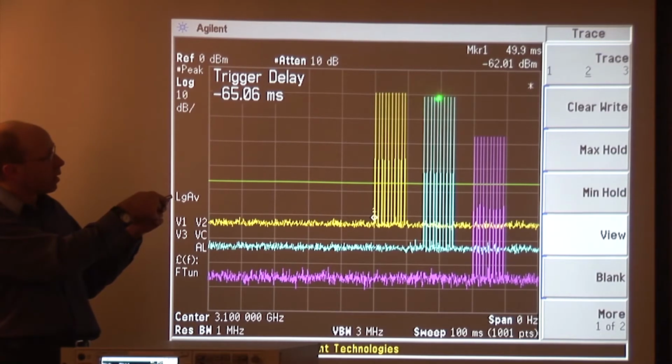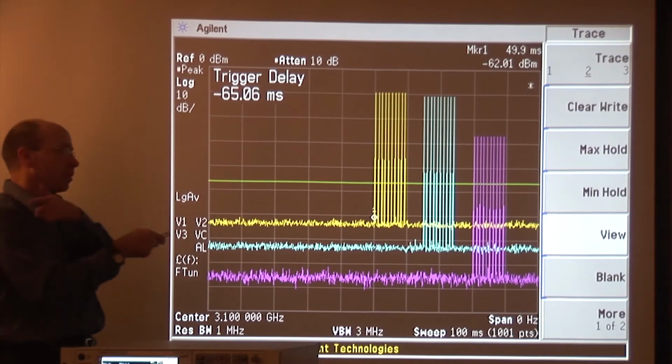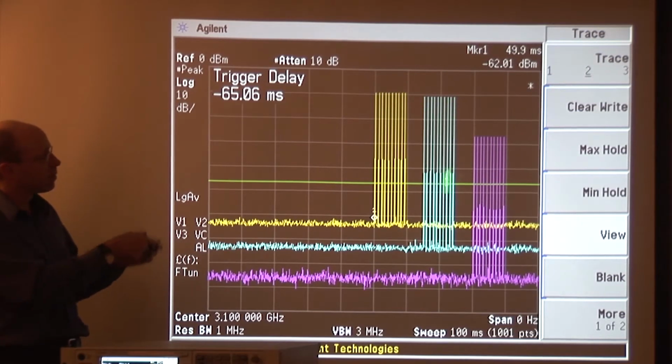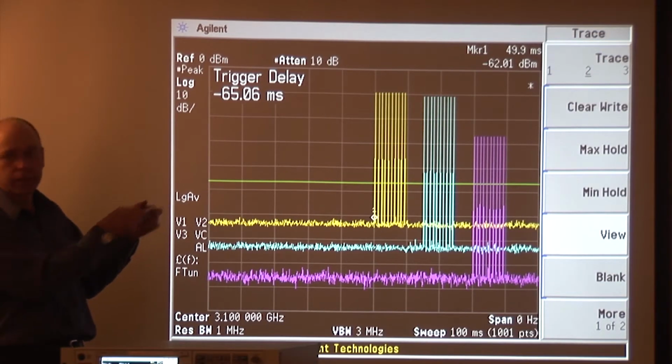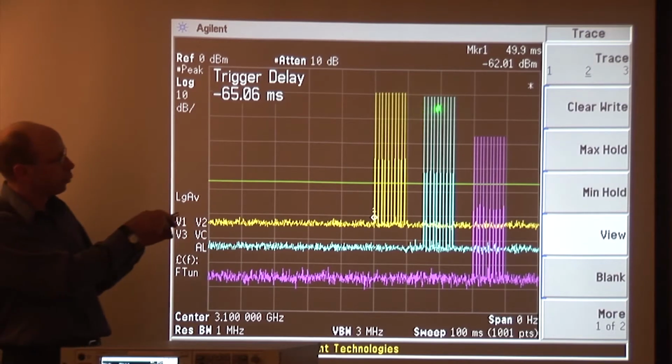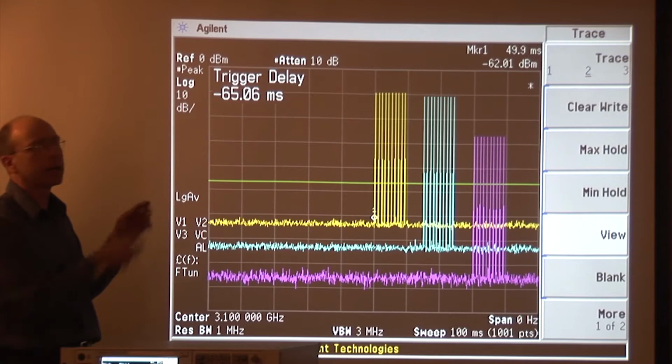Whereas here, we're equal to or possibly even a little less than the width of that lobe. In fact, as Julie points out, if we were to not use 1 megahertz but use 2 megahertz right here for the 1 microsecond pulse width, we'd actually bring that up to about there. We'd get a little extra there. So here we are just technically a little narrower than that lobe right in there.